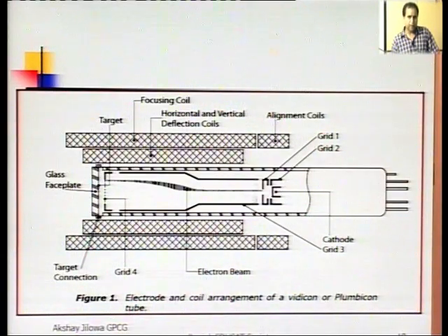Here we have alignment coils, as we discussed in the previous section. Alignment coils keep the electrons aligned throughout their journey. Then we have the focusing coil, which runs right from the beginning till the end of the tube. Its purpose is to keep the electron beam focused. As we can see from here, the electron beam is a little scattered while it bends away from its mean position. Why does the electron beam bend?